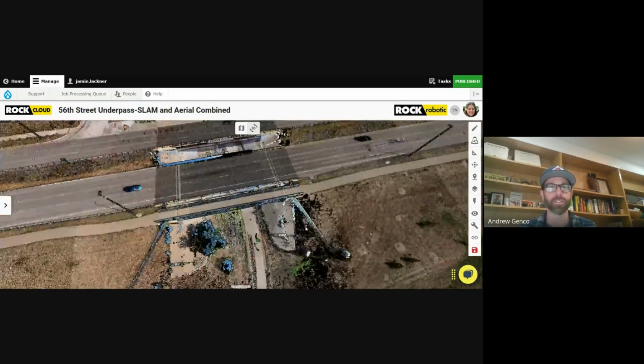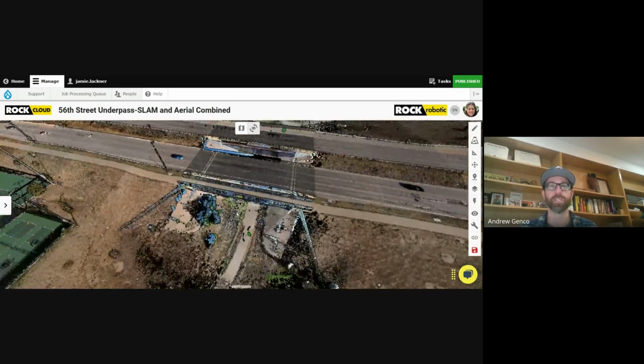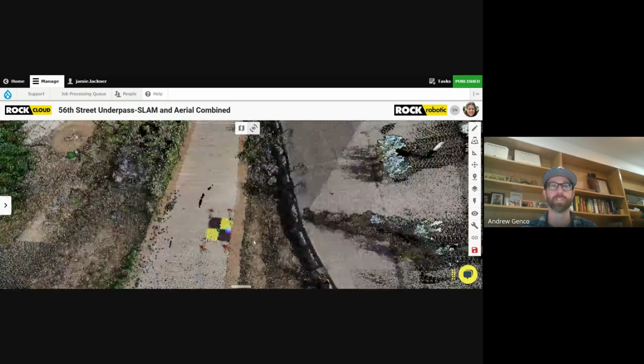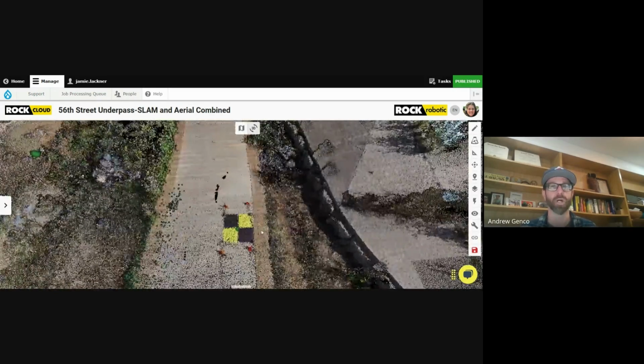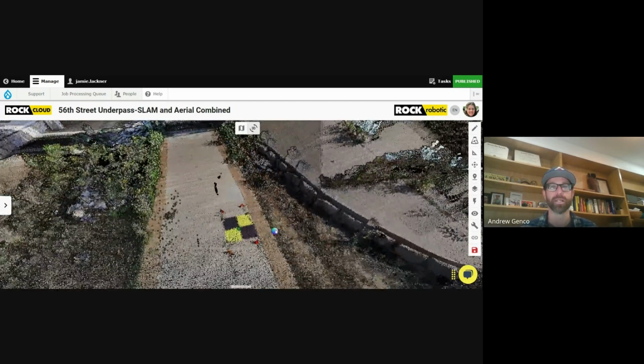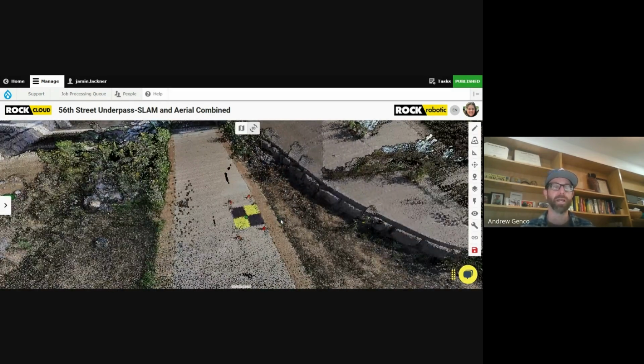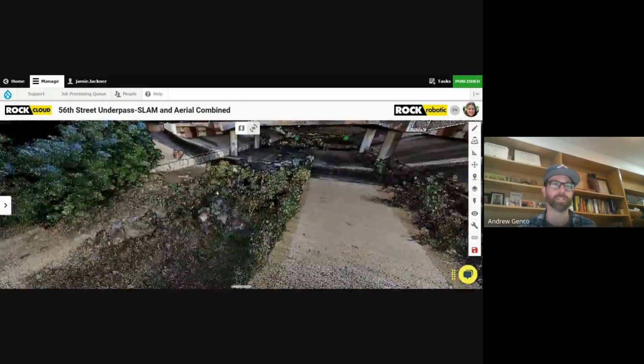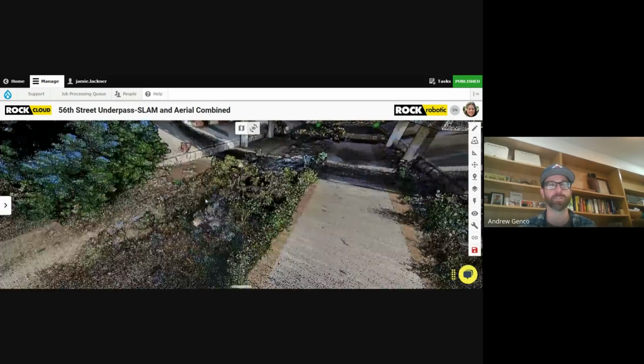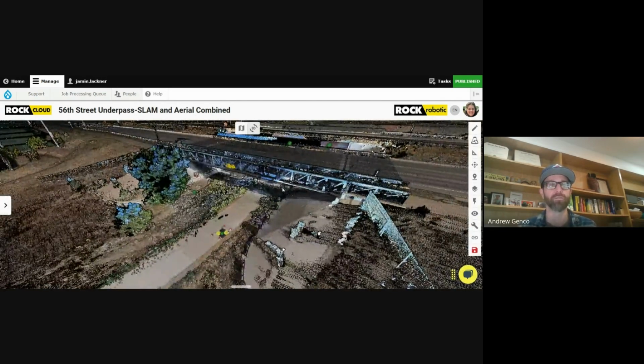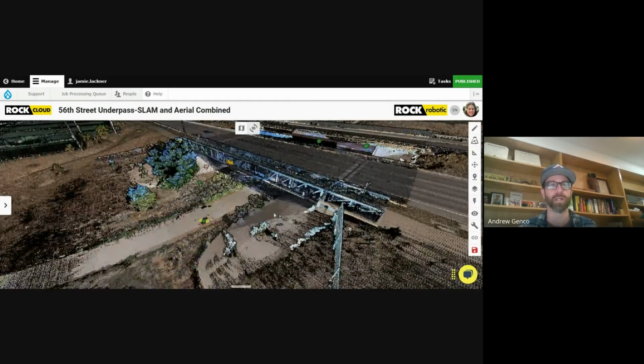And then accurate surveying. Each GCP should be surveyed in correctly using a GNSS rod and antenna. And with that, please keep in mind that nearby obstructions can reduce the accuracy of that surveyed GCP location. So we had to move away from the overpass to ensure that wasn't going to be an issue.